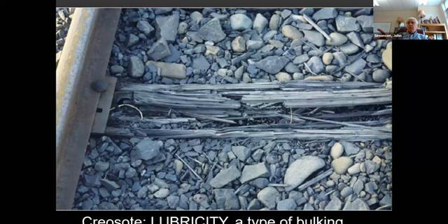So the rails are steel, but if you look at the shape of them as the train goes over them, they're a wave, because where the weight of the wheel pushes down, they'll actually move down. And if you watch the rail, it will go up and down, kind of a sinusoidal motion as the train passes. The spike is like a giant nail, and it goes to the cross tie. If the cross tie can move a little bit also, that's called lubricity when you use creosote. That actually gives you a longer service life for the railroad tie.